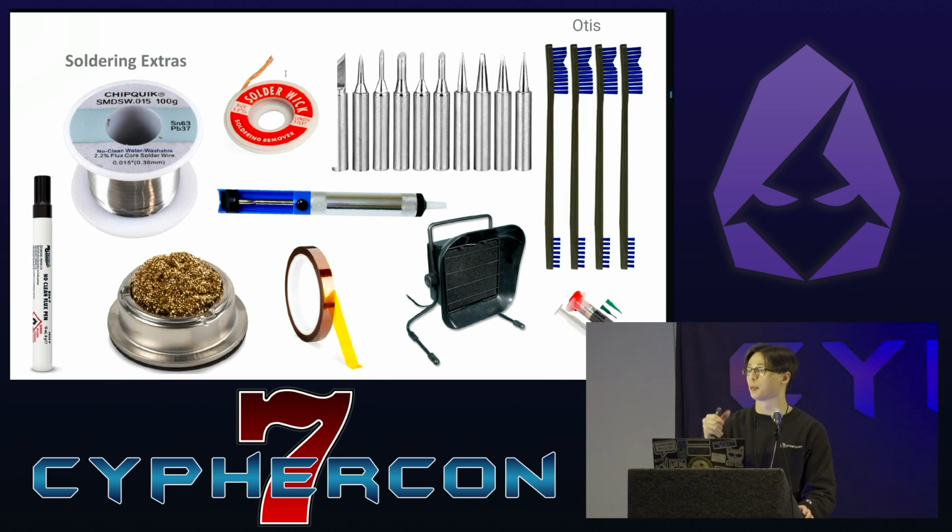With the solder sucker, there's a plunger that you depress, and it holds into place. You hold the tip of it up to the solder you're trying to remove, melt it with the iron, and when you press the button, the plunger's released, and that vacuum force, hopefully, removes the solder. Sometimes it takes a couple tries.